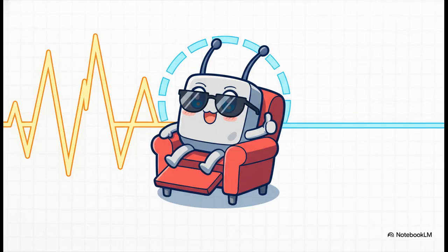The most straightforward software trick is just to make the program wait. It sees that first voltage drop, and then it literally just stops. It sits in a tiny loop for a fraction of a second, which is just enough time for the physical switch to stop bouncing around.